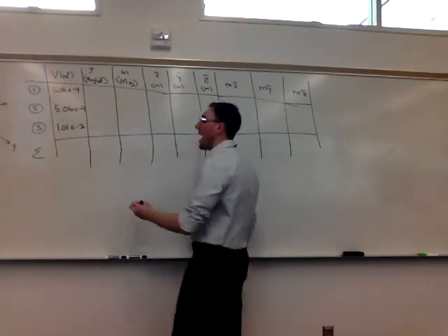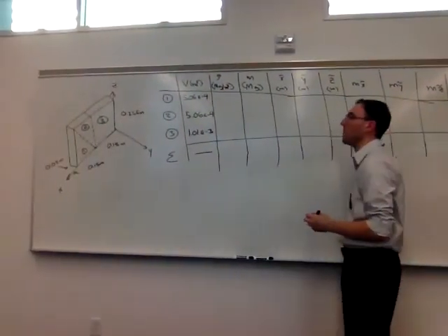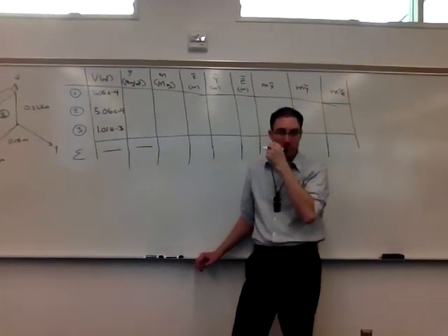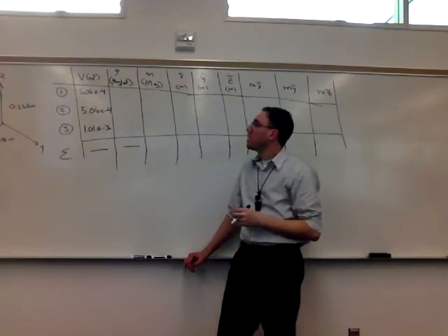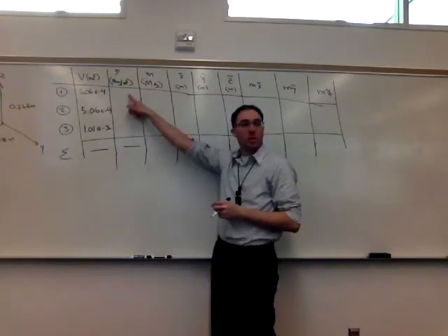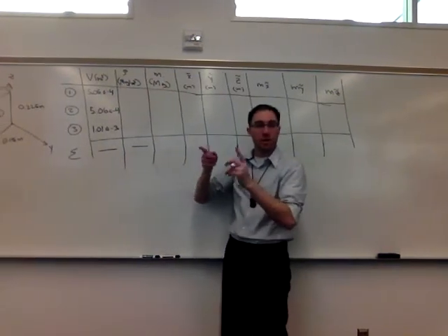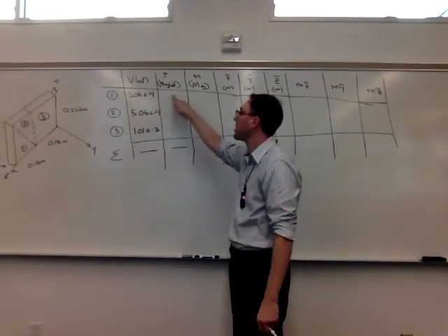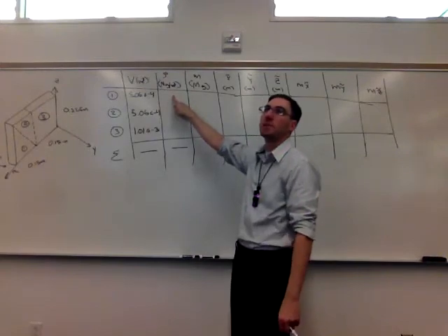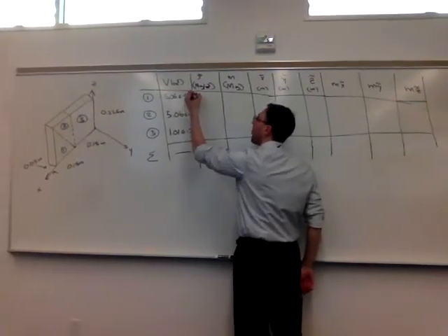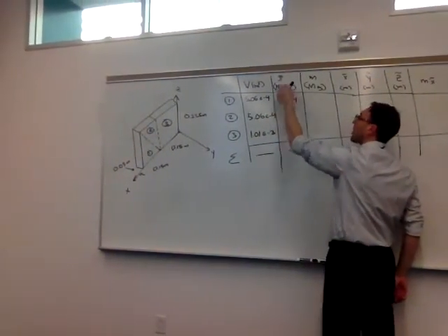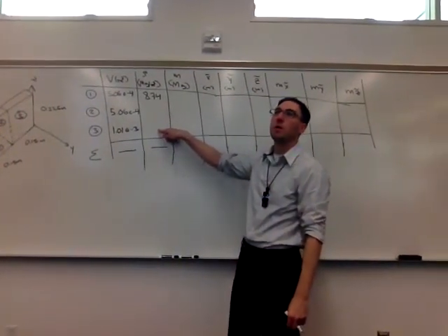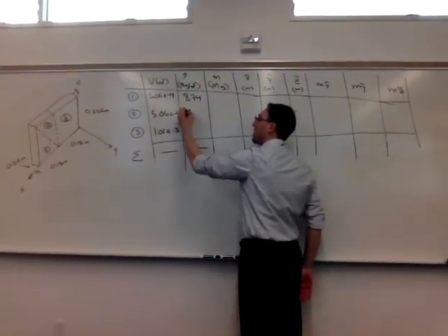Because we're looking for the center of mass, we're not going to add the total volume. We care about the total mass of the object. So this is where now we're going to account for the fact that it's made of, in this one, 2 different materials, but it could be more than 2. So shape number 1 is the brass, so we need to include the density of the brass. So that was the 8.74 megagrams per cubic meter, whereas 2 and 3 are both made of the steel, which is the 7.85.